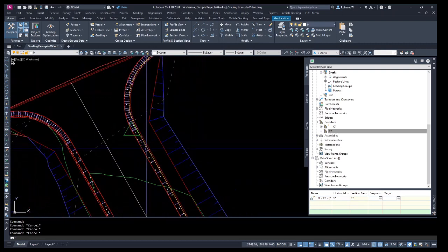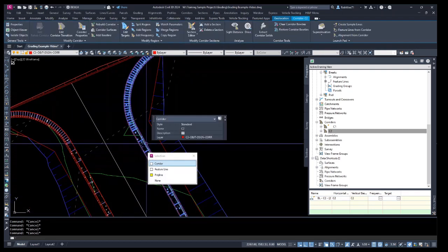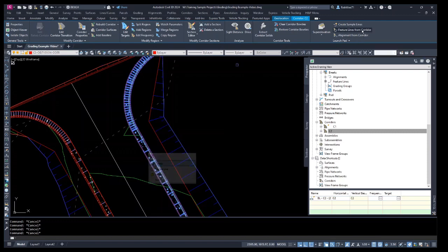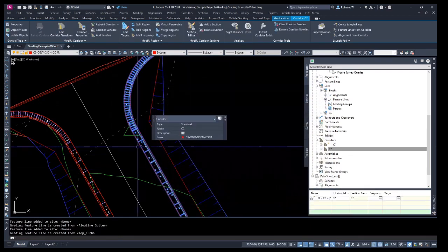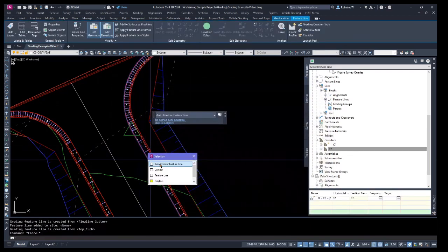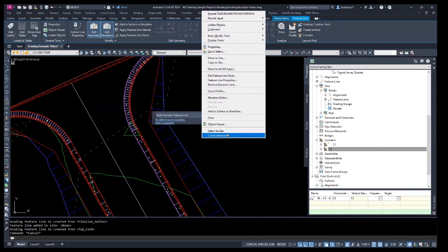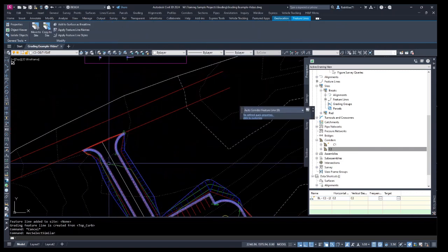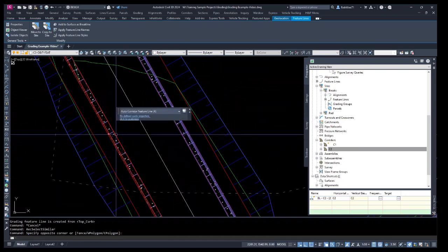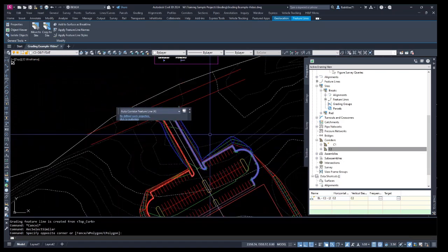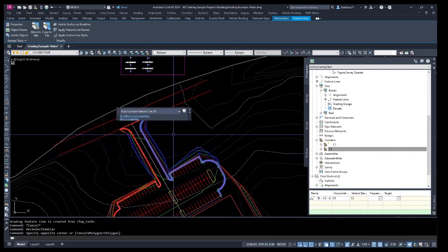Now we still need to go ahead and extract our auto corridor feature lines from this. We're going to get all of them. There they are. Hit extract. Now here you could select an auto corridor feature line and then select similar. Be careful, it will grab the ones you've already selected, but you can shift select. That way it's a little faster in grabbing all of those.